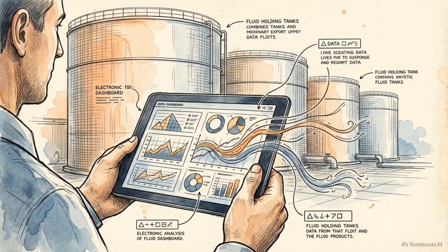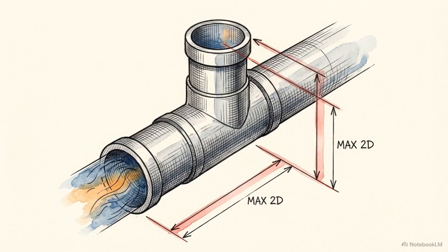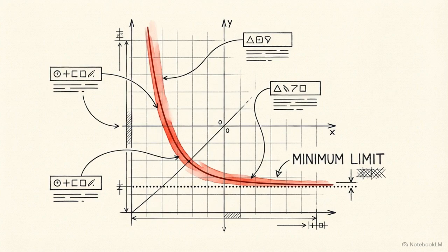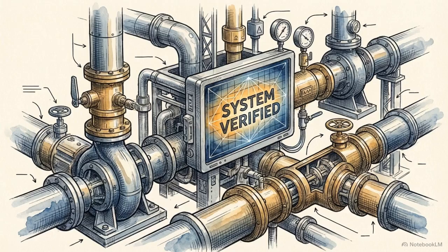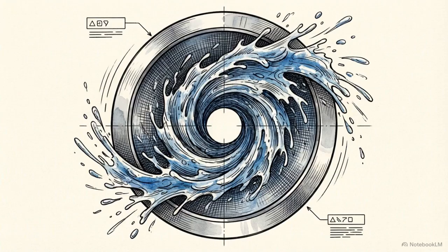When an auditor reviews the facility, they look for exactly this data. They expect continuous velocity logs, verifiable dead-leg dimensional tolerances, and detailed Reynolds number calculations, modeled against worst-case usage scenarios. Regulators do not assume sterility simply because expensive equipment was installed. They require continuous mathematical proof that the system maintains exact hydrodynamic performance thresholds. A compliant high-purity water loop is a kinetic defense system. By maintaining rigorous mathematical control over the Reynolds number, engineers actively build sterility into the physics of the flow.